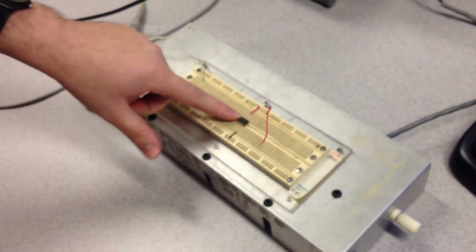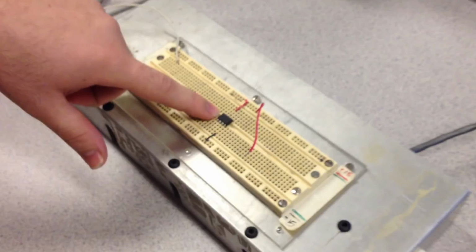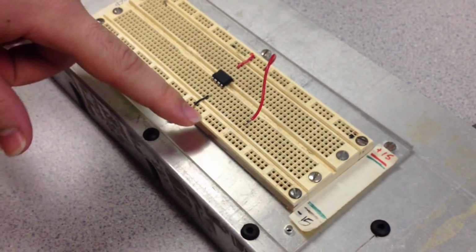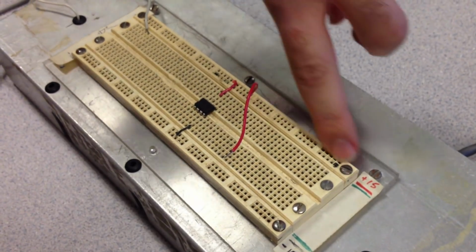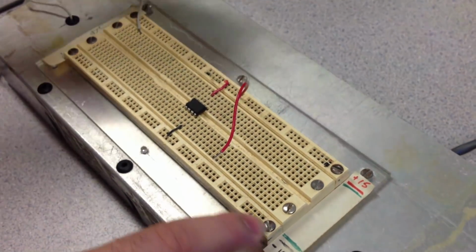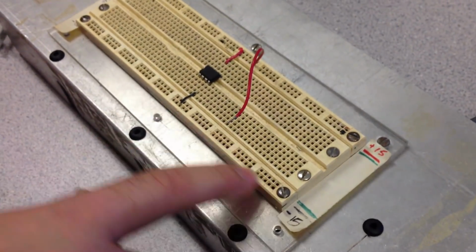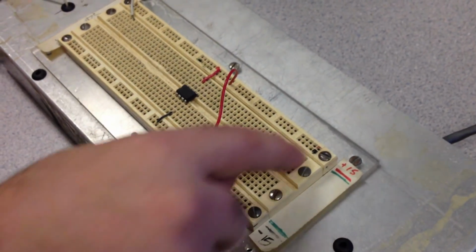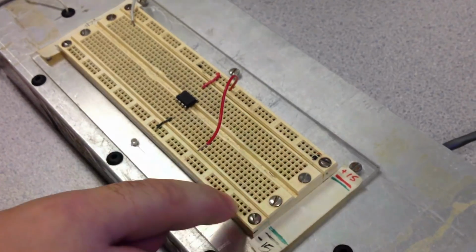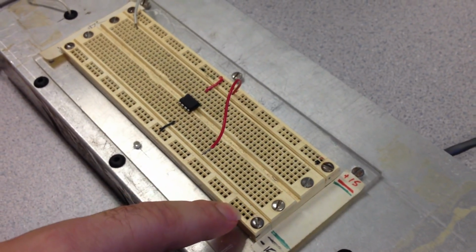When you come to the lab, you will find this breadboard. As you look, it has an operational amplifier here. This board contains the positive supply. This is the last grid here. This is plus 15. The last one is negative 15. And the grounds are the inner one here and the inner one here. So it is plus 15, ground, and minus 15.